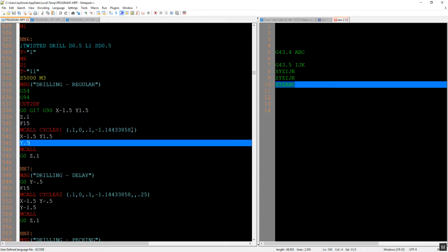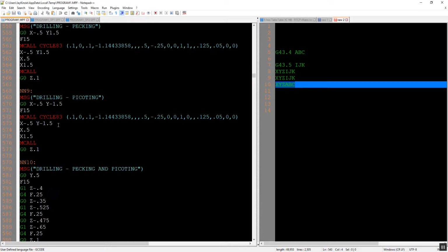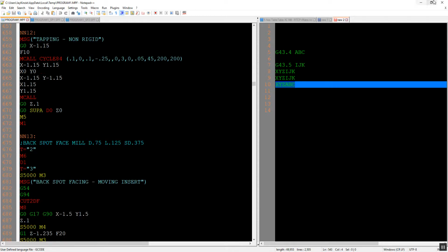But just looking at it, I forgot what that stuff was. I'd have to look it up. But it's just one manual away. And you can see it on the machine anyway, so it's not really a big deal. And then change it graphically. But that's basically what they look like. So, they've got the standard G81, G82, G83. It also supports peck tapping, which is super cool. And a whole bunch of reaming cycles and backboring and a whole host of things.